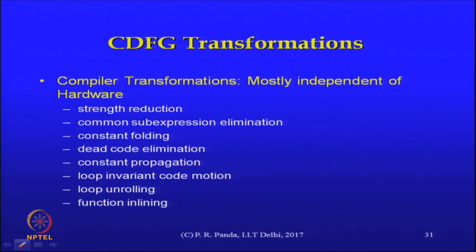These are early transformations. They are also called compiler transformations simply because all of these techniques have something in common with the typical early optimizations that happen in a compiler. Some of them are straightforward, some of them make sense perfectly well in both contexts, irrespective of whether the output is instructions in a compiler or hardware as it is in synthesis. Some of them are a lot more interesting.